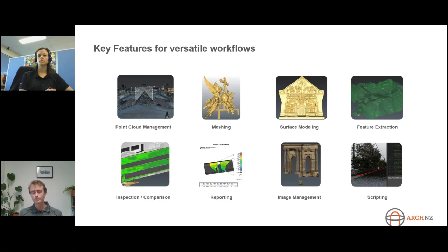The key features of the software begin with point cloud management. It's really powerful in terms of clipping, slicing and dicing your data, cleaning your point clouds with autonomous routines or manual modules. It then has, and this is where the real power in the software is, the meshing algorithms. It has fantastic methods of creating complex meshes or meshes of surfaces. You can then extract features from those meshes or from the point cloud directly. And then there's powerful inspection and comparison tools which output reports that you can deliver to your customers. And then there's a scripting engine as well, as I mentioned earlier.